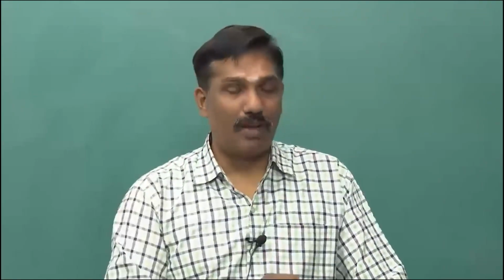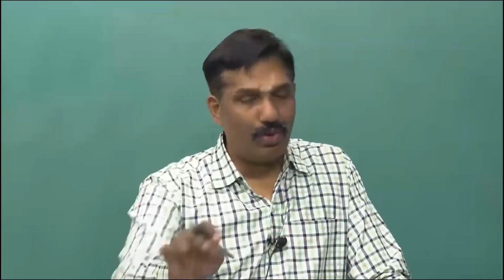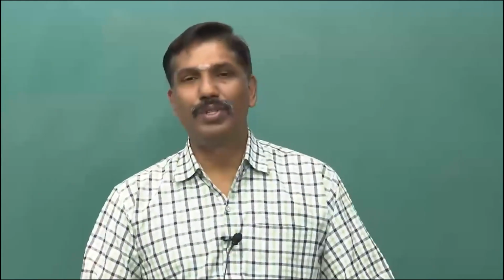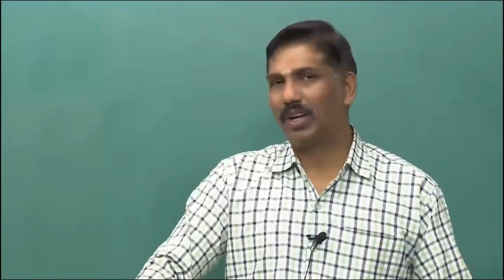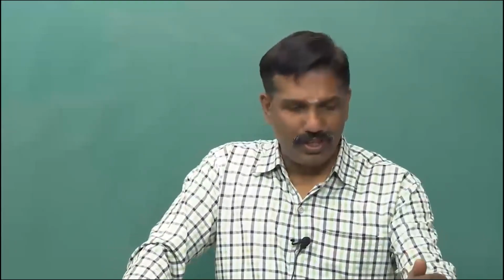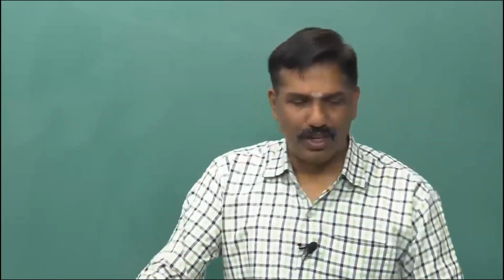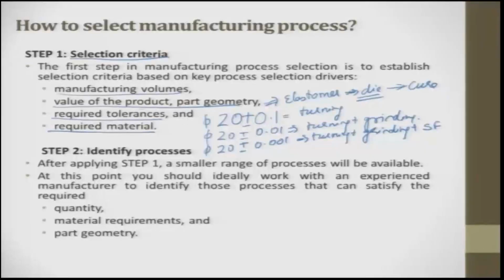So, depending upon the application, if it is going to be high temperature, then you choose a ceramic. Then when you choose a ceramic, you do not use a subtractive process or a deformation process, and casting is not thought about. So, based on these 4 points, you keep it as a selection criteria and decide the process.